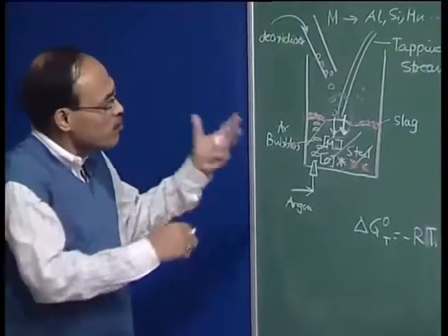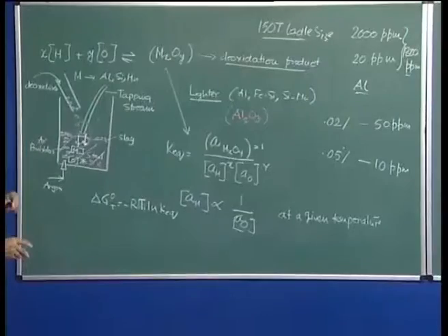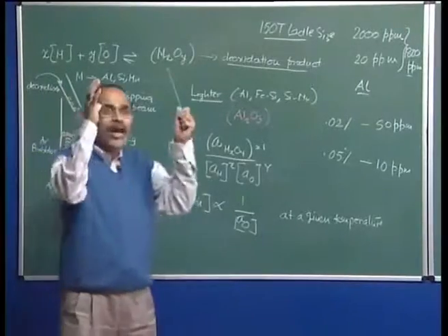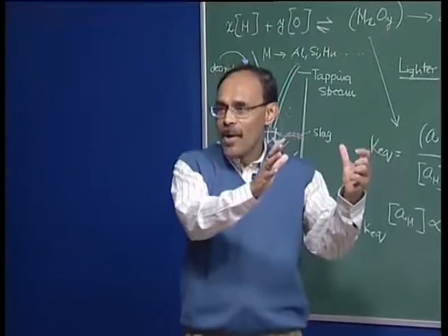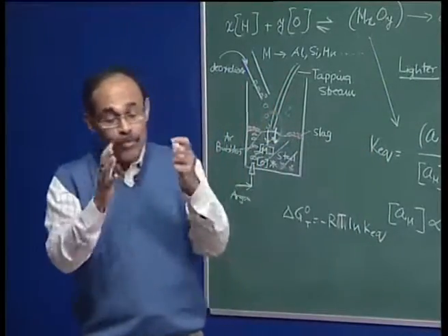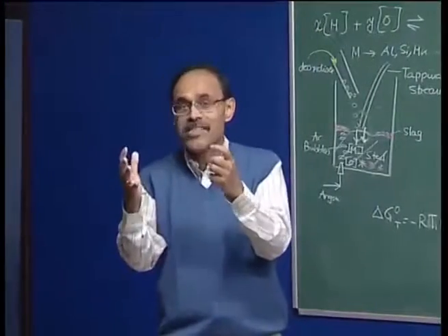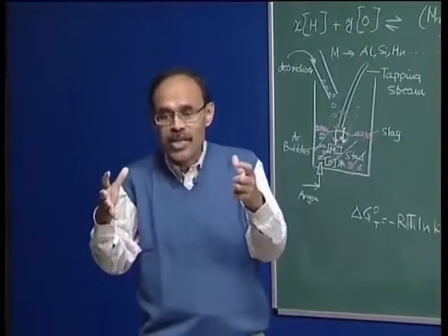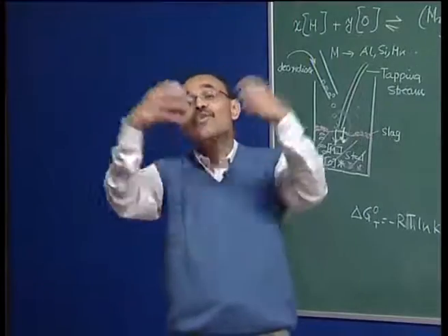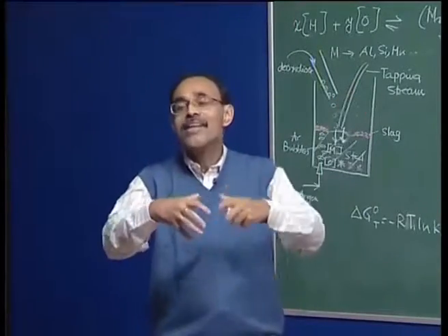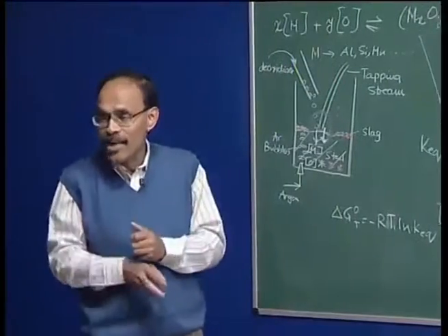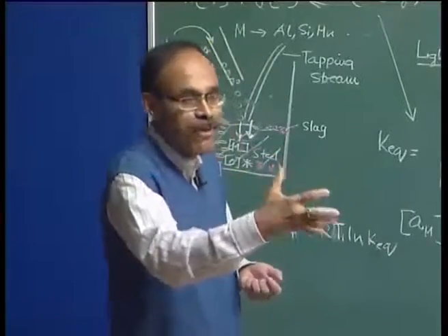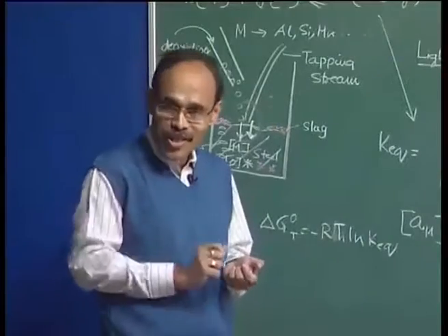lecture and give you an overview of the deoxidation process, I must say that we have primary steel making. The bath is rich in oxygen. We have to remove oxygen from the bath, because we know that if it remains, there is so much oxygen that during solidification, oxygen is going to be evolved because solid has less solubility than liquid. So the oxygen present in steel is going to impair the mechanical properties. So before we process steel further, we would like to take out oxygen first.